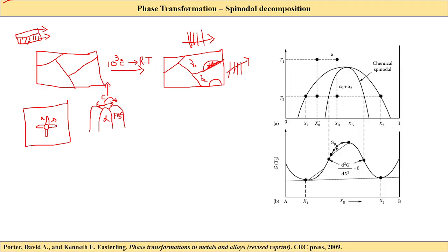Because there is a chemical potential gradient or a concentration gradient, Fe3C will consume more carbon, right? Carbon is less here and more here, so carbon will try to diffuse from here to here, which is dC/dx, and you multiply it with the diffusivity of carbon, then you will have a molar flux of carbon diffusing from above the surface of alpha to Fe3C, right?